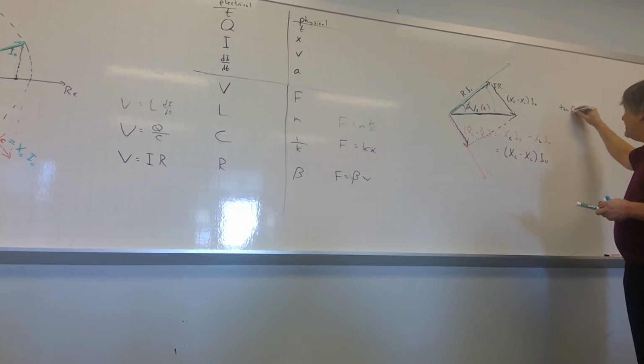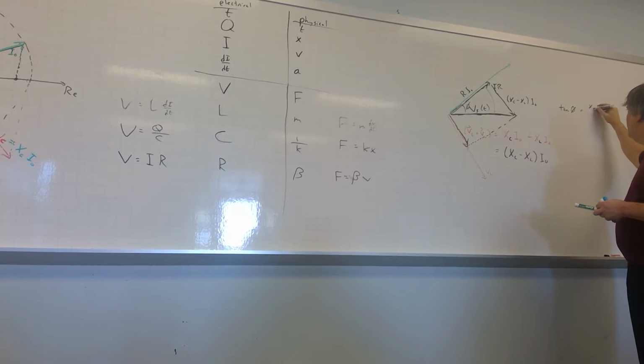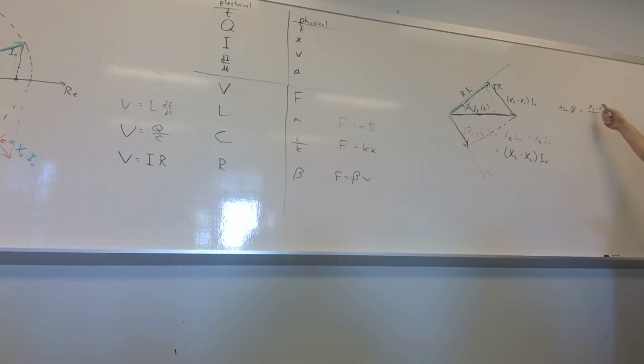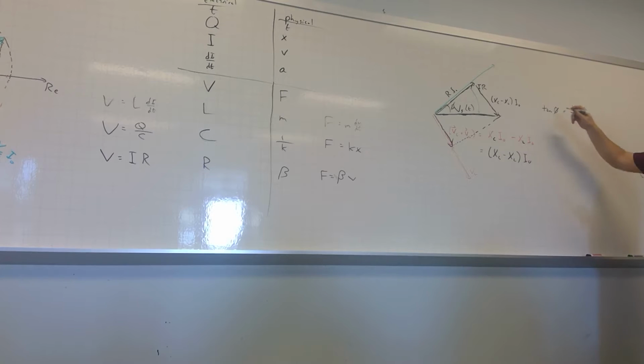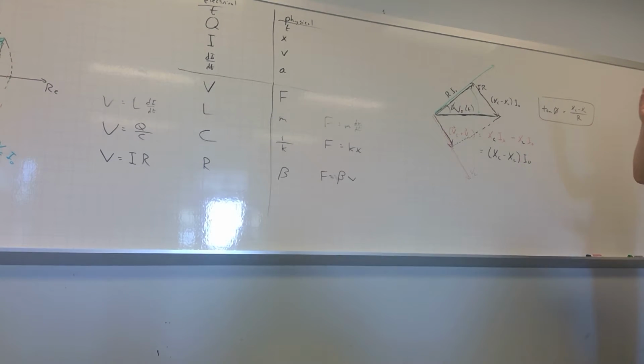Looks to me like the tangent of that phase lag would be the overall difference in impedance between the capacitor and the inductor divided by the resistor. If we had done the differential equation out the long way, this would be what we ended up finding for that arbitrary phase lag that we put in there between the current and the voltage.